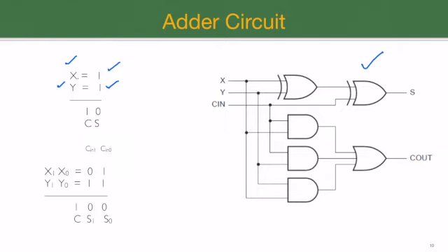Just like the decimal numbers, when we reach the value of 9, after that it becomes 0 1. Similarly, in the binary, when we reach the value 1, the next one is 0 and 1. So 1 and 1 added produces the sum result as 0 with 1 as carry. Because there are no bits over here, this 1 is our result. So when we add 2 bits with the value of 1, the result of the sum is 0 and the carry is produced, which is 1, and therefore the complete result becomes 1 0, a 2-bit result.